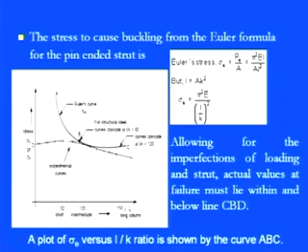We could simply figure out that in this plot of sigma E versus L by K ratio, the experimental part is a pretty realistic way, and below this CB line, that means you see this D point here, this C point here and this B point, we can say that these are the real actual values at failure, and they have to lie within this particular range.